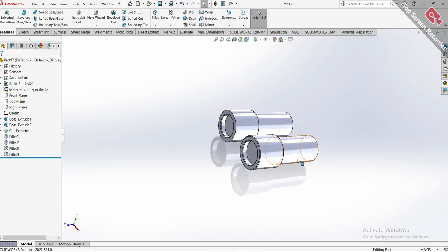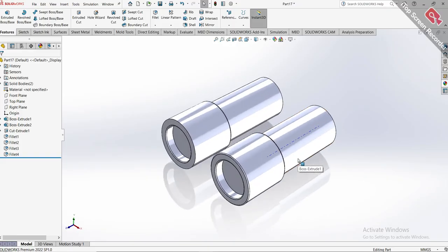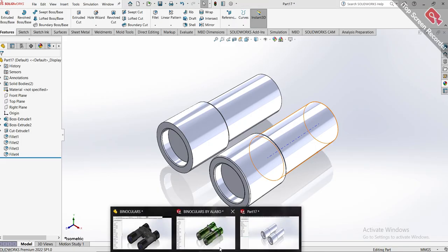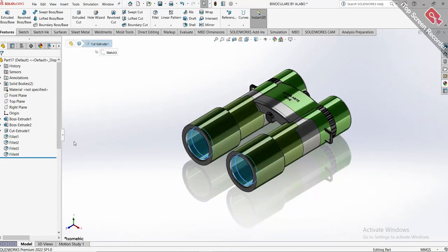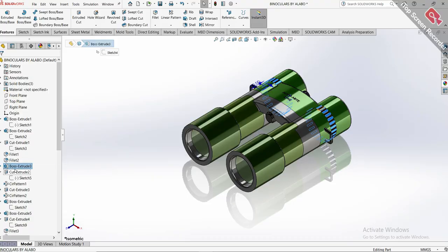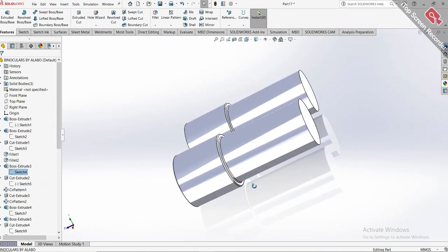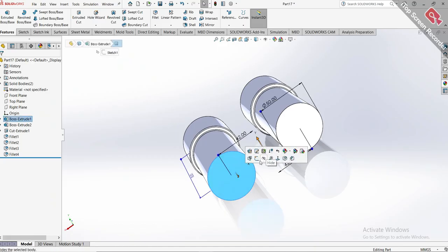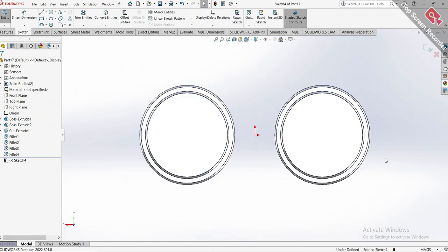So as I said earlier, we're always making reference to the other previous work to see if there's any other step that we need to follow. So we're done with the fillet. To come to this side, come to the sketch. That's this sketch. So we have to go back to our work. Come here, click on sketch. We'll have something like this.